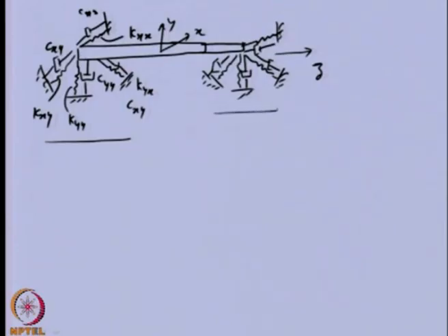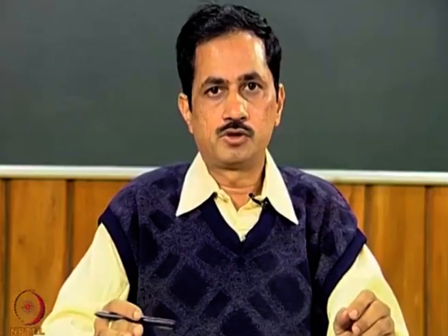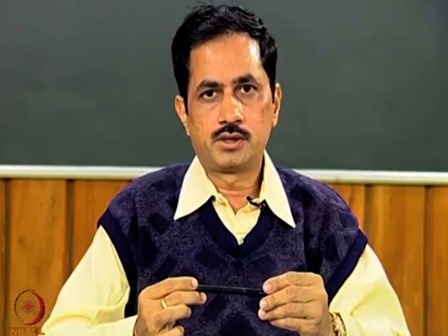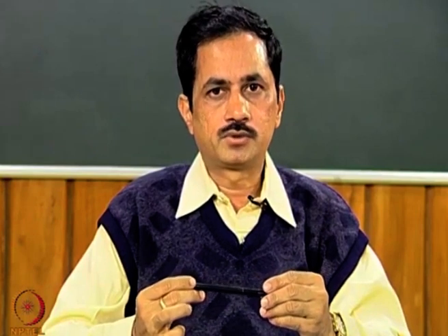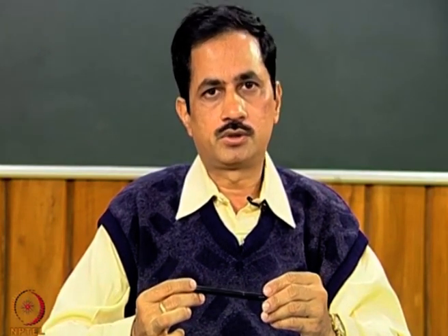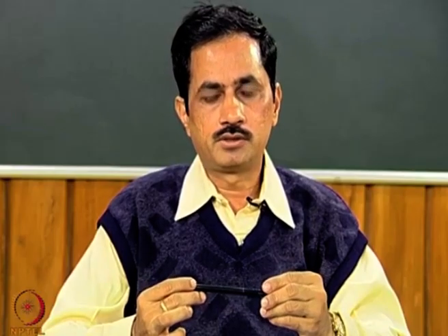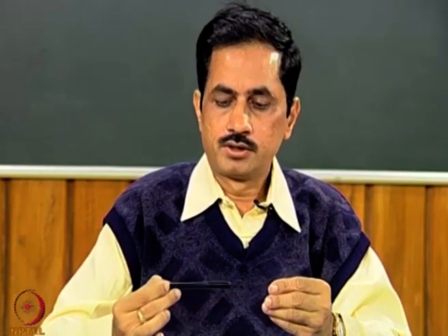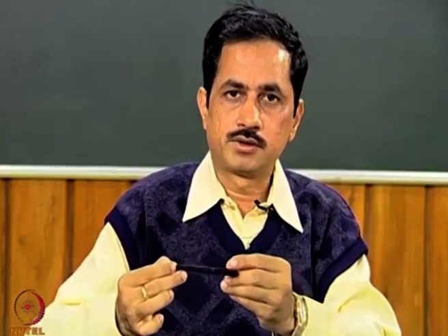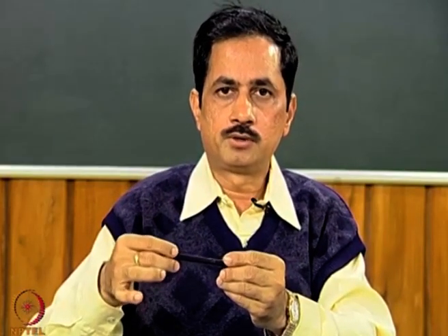So, when we draw the free body diagram of this particular rotor on similar lines as the previous lecture, let us say I am drawing the free body diagram in the YZ plane. In this particular case also we are assuming that we do not have any coupling of the translatory motion and the rotary motion; they are uncoupled. That means, if you give a shaft a vertical motion or a vertical force, there will not be any tilting.